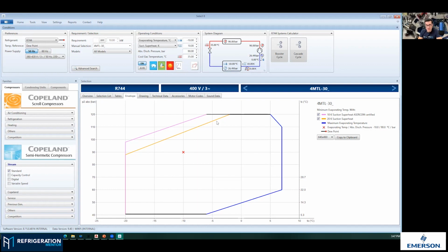This is why checking that discharge temperature is so important, along with getting your pressures and your volts and your amps and putting this all together. Because we are actually detectives out there looking for this information. At the end of the day, if that compressor failed, there was a reason why it failed. And we got to figure out why, because I've seen so many compressors over the years that were just replaced, and then that one failed again. I even did lots of them over the years because I didn't know the difference.